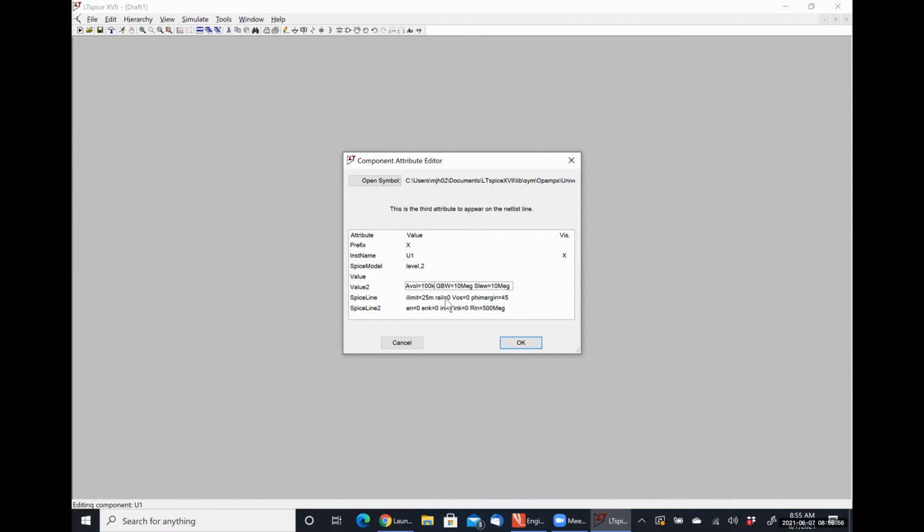So what that means is that in a real op amp, previously I said that the output voltage can never exceed the supply voltages. That's true for a rail-to-rail op amp. For a non-rail-to-rail op amp, there's actually a specific offset voltage below the supply voltages that you can't exceed.